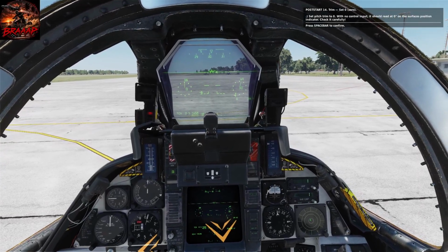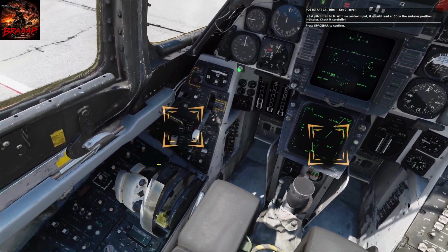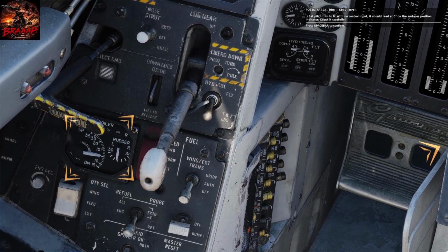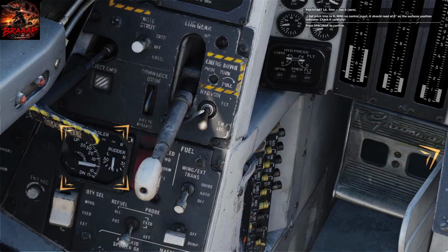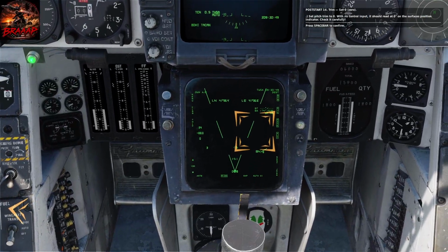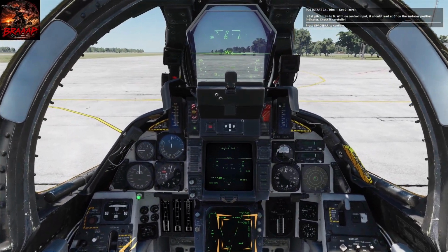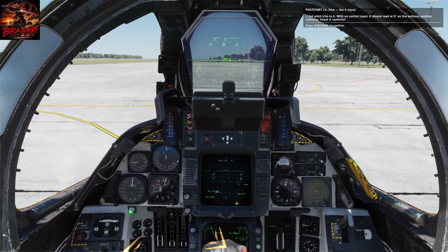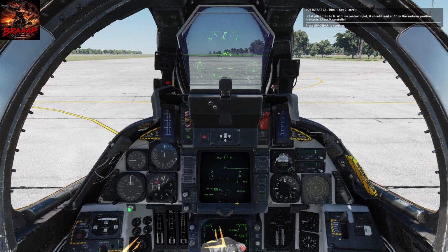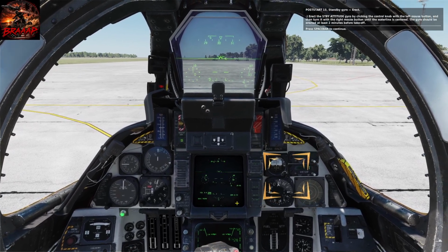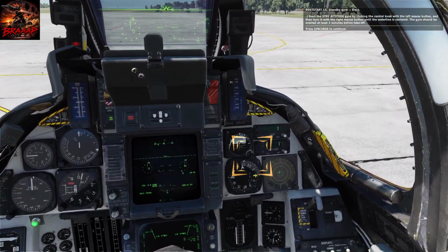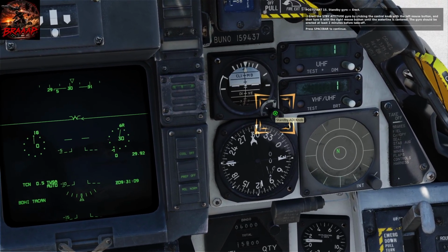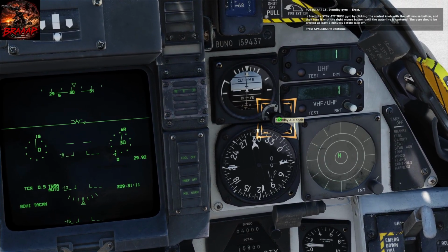Set pitch trim to 0. With no control input, it should read at 0 degrees on the surface's position indicator. Check it carefully. Press the spacebar to confirm. Erect the standby attitude gyro by clicking the control knob with the left mouse button, and then turn it with the right mouse button until the waterline is centered. The gyro should be erected at least 2 minutes before takeoff. Press spacebar to continue.